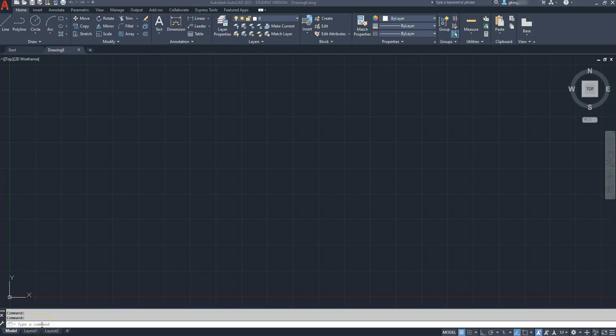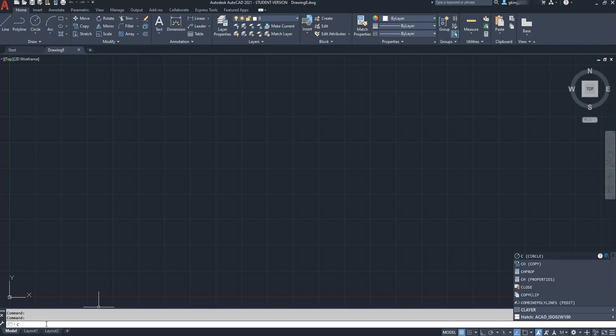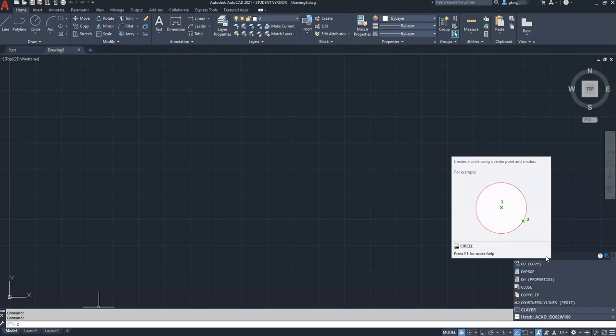window. So this is personally where I learned AutoCAD, and I'm a very prompt driven or command driven AutoCAD user, so I'm going to try my best to show you multiple ways of doing things. But say for example that you wanted to do a command such as draw a circle, right? So I click down to my command and I type in C, and you'll see on the right hand side of my screen every command that starts with the letter C comes up, and the first one is circle.